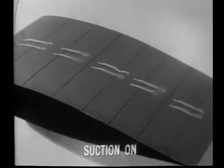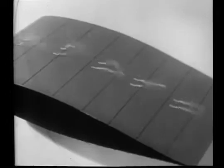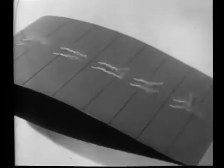The flow over this profile is completely separated, as shown by the violent action and upstream direction of the tufts. Suction reattaches the flow. This is also reflected in the pressure distribution.